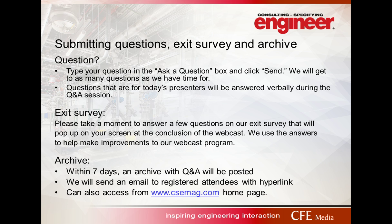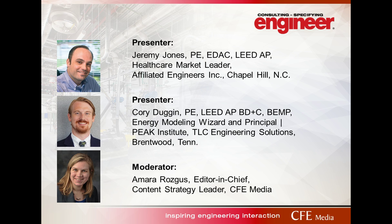But in a lot of climates, in northern climates and in southern climates where it's hot and cold outside, I have seen the load be significantly higher, especially in places like operating rooms. There's a lot of equipment in operating rooms, especially specialty operating rooms like a cardiovascular OR or a neuro OR. If the minimum in an operating room is 20 air changes, the load-driven maximum might be 30 air changes or more if they have a complicated surgery type with a lot of occupants that are sweating and a lot of equipment buzzing.